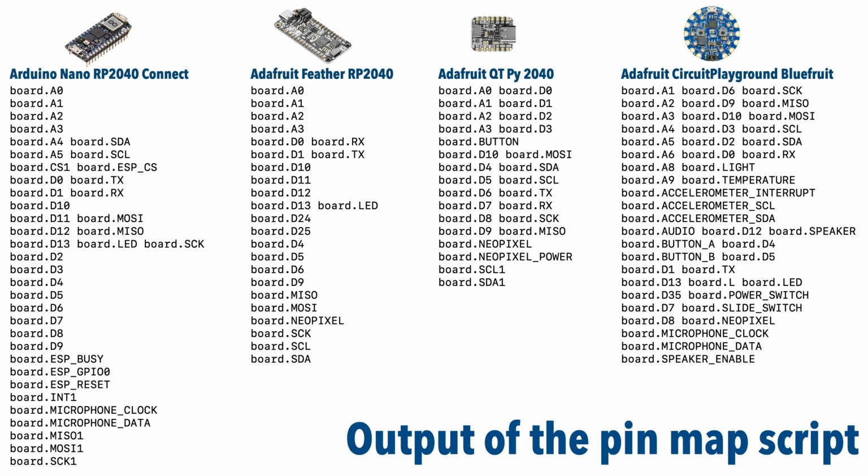Now, if we compare the output across other boards, we see that the Feather board's LED can also be called a D13. We see there's no LED on the QT Py, and for the Circuit Playground Bluefruit, the LED can also be called a D13 or even just L.